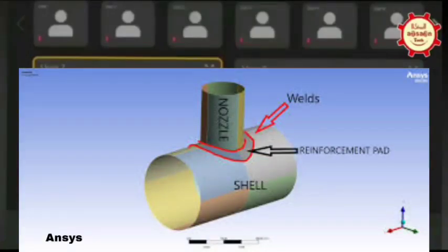Anybody face this issue? So you are getting a warning of gross structural discontinuity, is it? Correct. He's saying it's an overlap, but there is enough distance. From the limit of reinforcement, that means from the edge of the pad? No, there is no pad. So what I have done, I limited the diameter to 75 mm only.